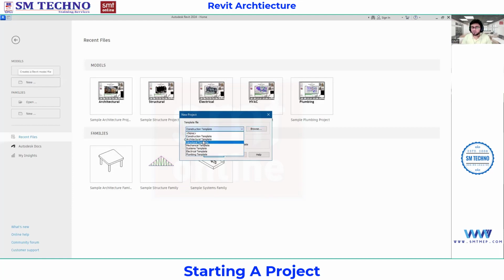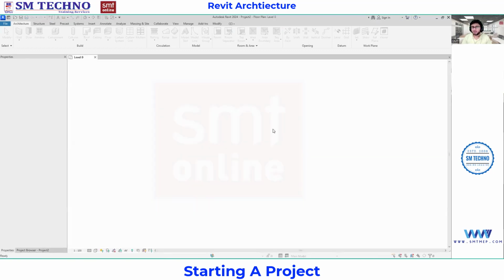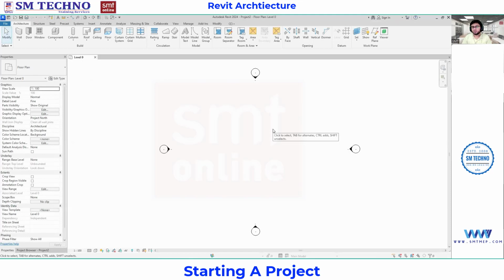But I am going with a basic template, which is given by Revit. So in the official template, I am going to click here project. If you want to create a template, select the none option from here and you can select the project template from here. And from here, you are able to create. It is up to you. But right now, we are not interested in creating a template because by default, templates are provided by the consultants. So I'm selecting the official template and clicking OK. Once you click OK, you will be getting the screen of Revit.